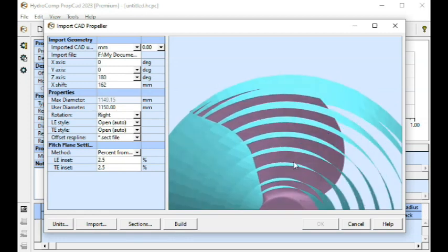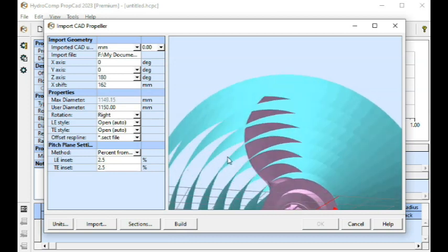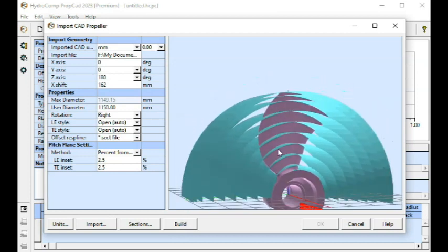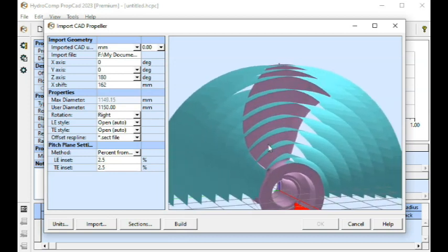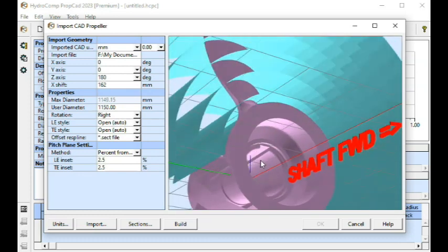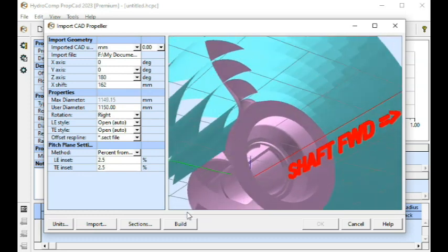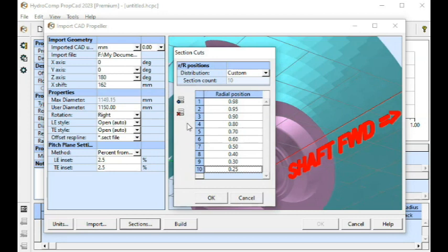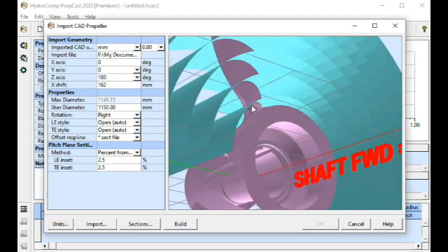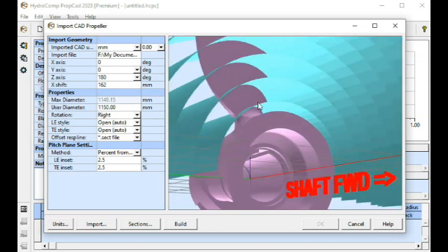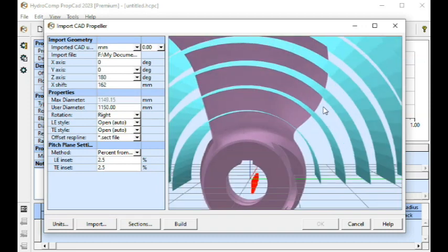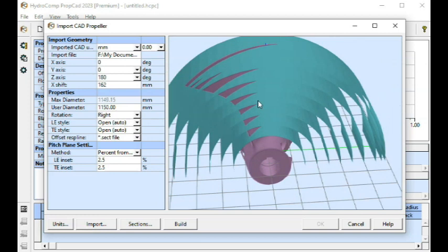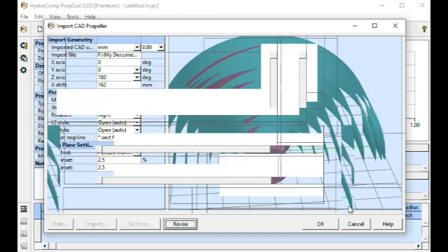And I think the only other thing I'm going to look at here, yeah, we really can't do a 25 here because of the cone shape. So I'm actually going to go in and delete the 25 out as well. All right, so now I guess that's as close as we can get there. All right, let's build it and see what we get. Build.